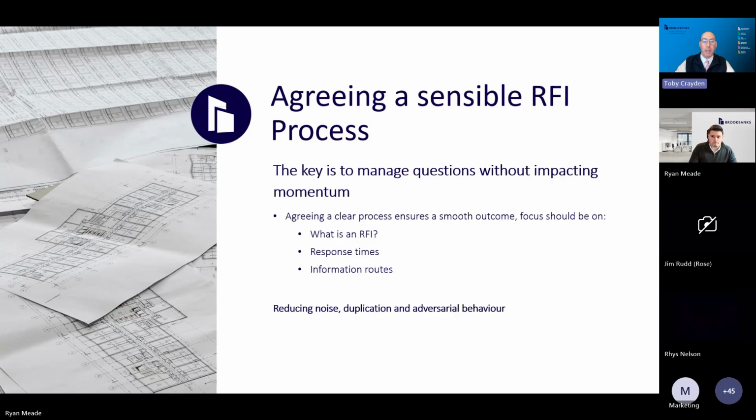Identify the issues quickly, make sure there's that clear line of communication, and perhaps most importantly, agree some sensible response times. Some RFIs will require near on instant decisions, perhaps on the phone, perhaps on an instant visit to site, but others perhaps not so much. And don't just lob all of the RFIs into the same sort of urgent category. If something can wait until a little bit more research has been done, or parked until it's a more sensible time to review, then fine, do that.